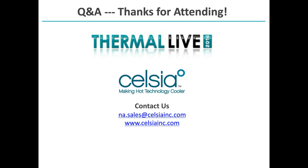Well, the area and length of the evaporator is generally fixed by what you're trying to cool. If I have a 1 by 1 inch heat source, then my evaporator is 1 inch. The condenser size is generally determined by how much heat sink I need. If I need 6 inches of heat sink, then that's what you have for a condenser area. So the application generally dictates what those are.